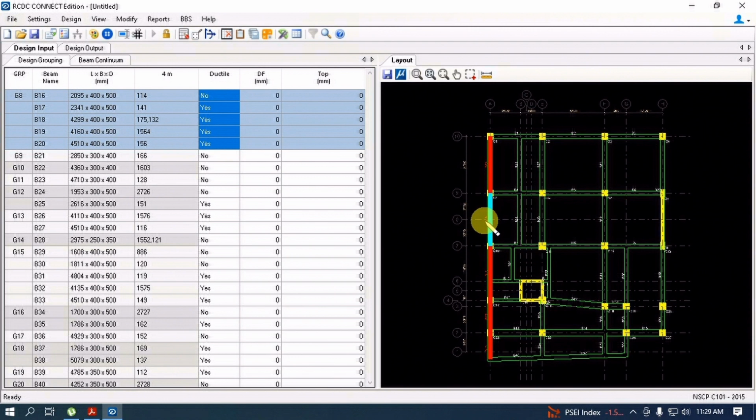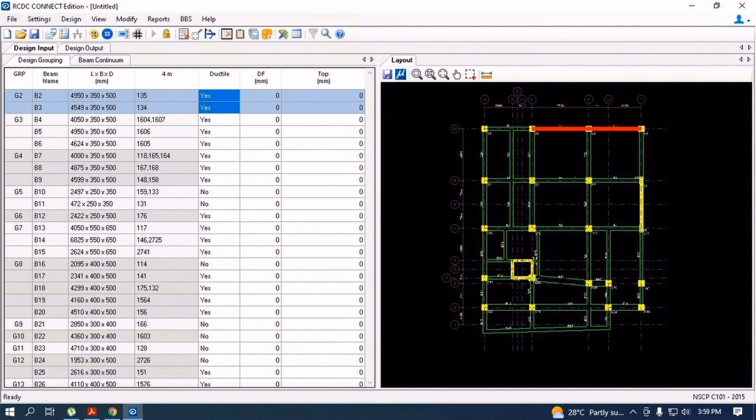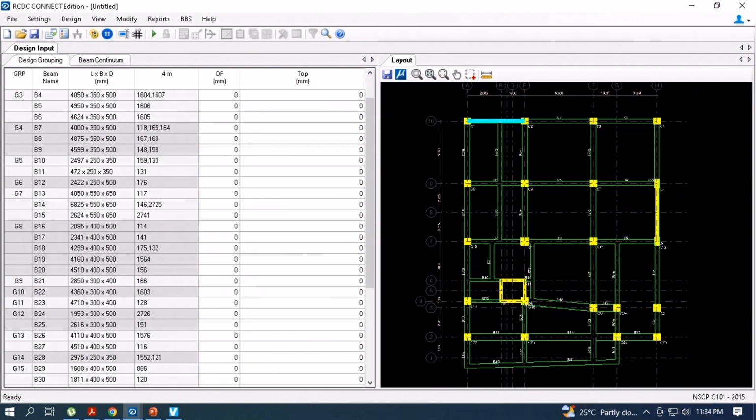The good thing is, once failed, it is easy to rectify. Just increase beam size and then everything will be fine. Another good thing in this method is, it would be easier to read and interpret the layout of steel reinforcement prepared by the software.